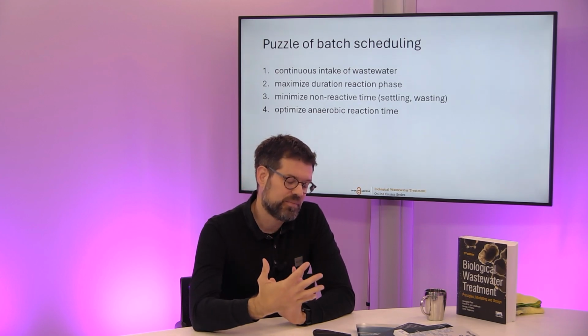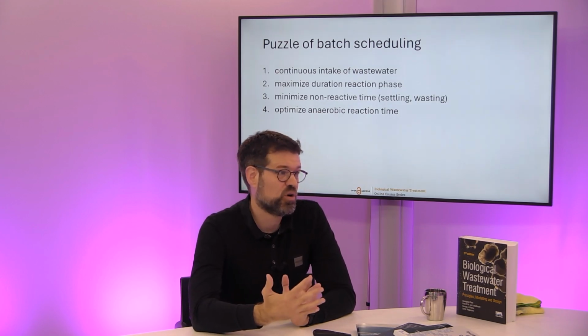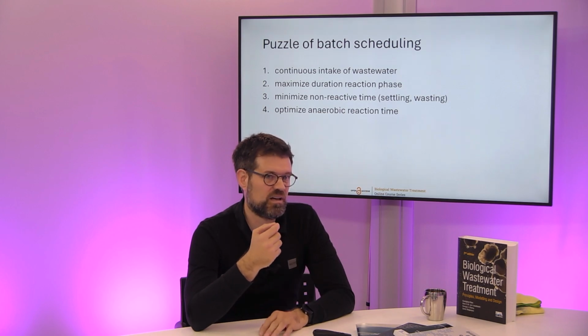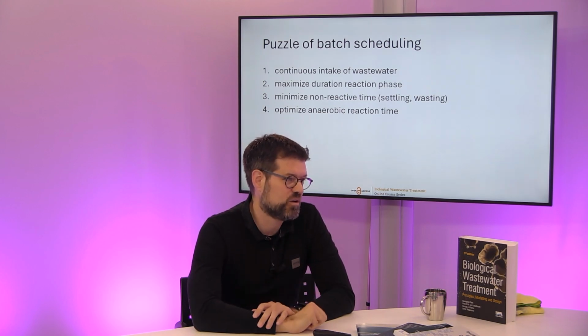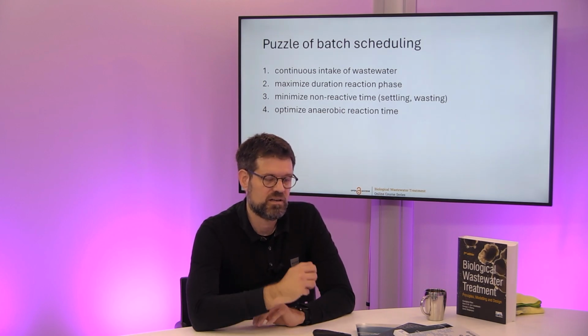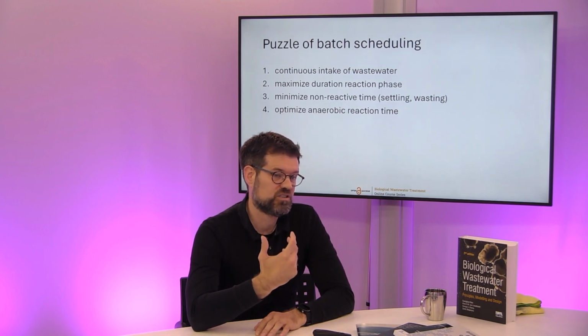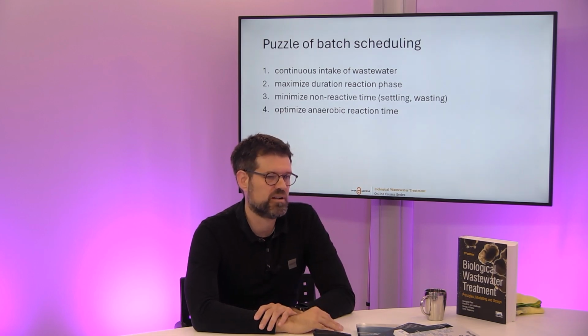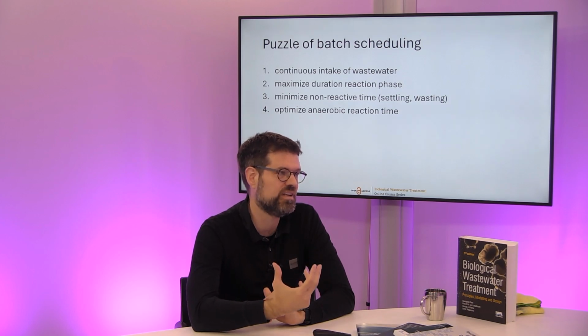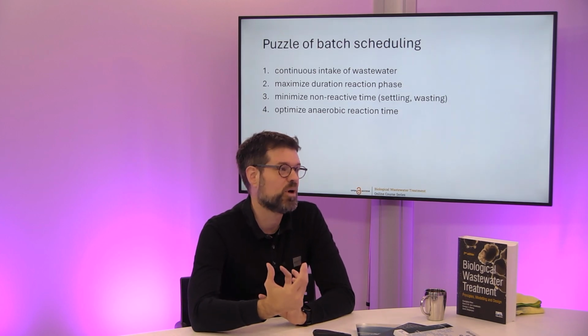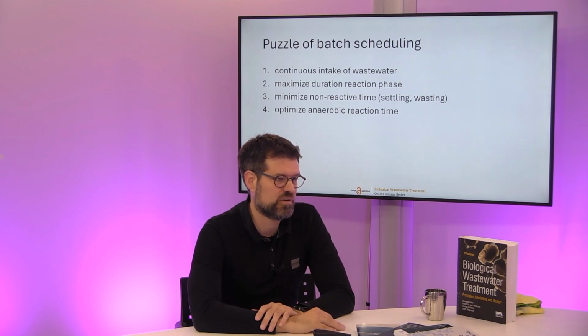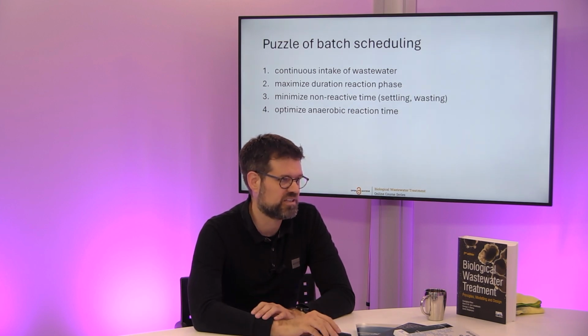At the same time, anaerobic feeding is important for the process because, as we learned earlier in the course, we take up substrate anaerobically in the aerobic granular sludge. So you really want to optimize your feeding phase so that you have the maximum uptake of substrate in the granules. So you have to optimize that anaerobic stage.